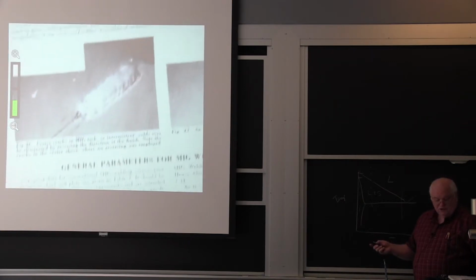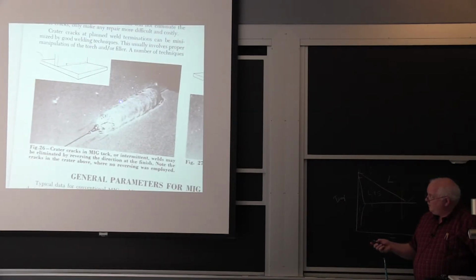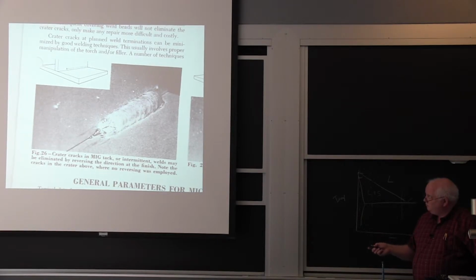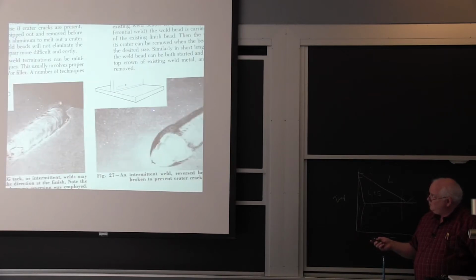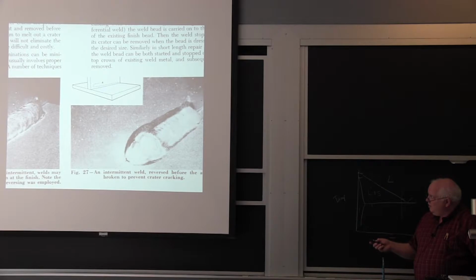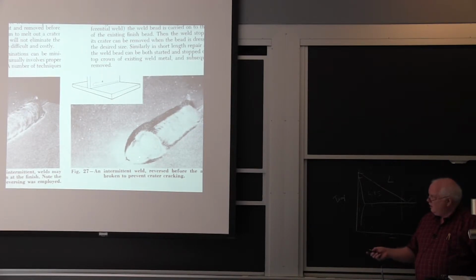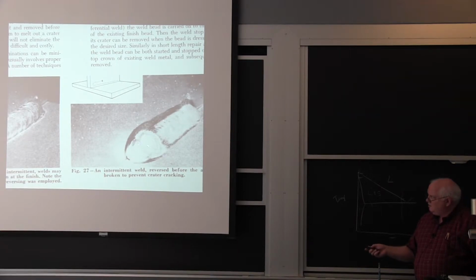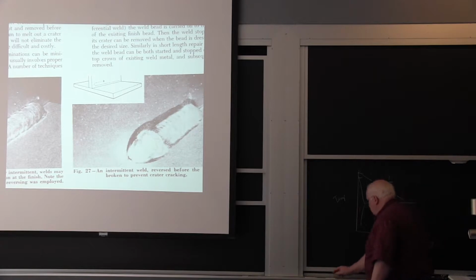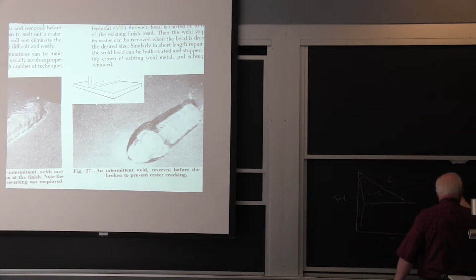So when you finish making a weld on aluminum, you're welding along, you don't just stop and pull the electrode off. Okay, because if you do, the aluminum shrinks 6% on solidification. What you should do as a welder, your welding technique, is you're running along, and as you get to the end, you backtrack, and you allow the backtracking to fill more metal in there so that your final cross section of your weld pool is not one that is concave.